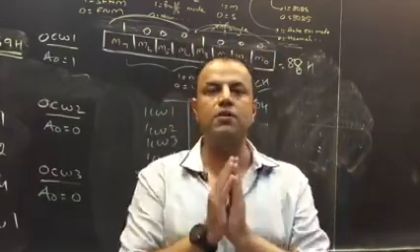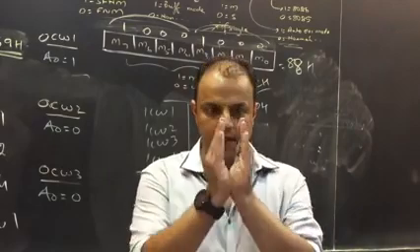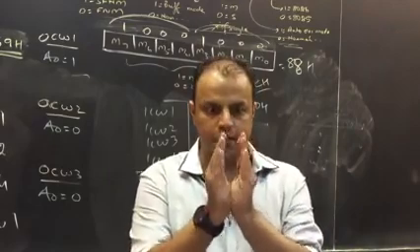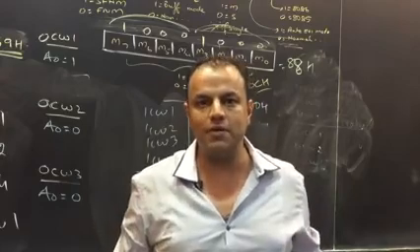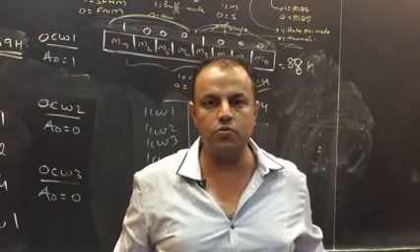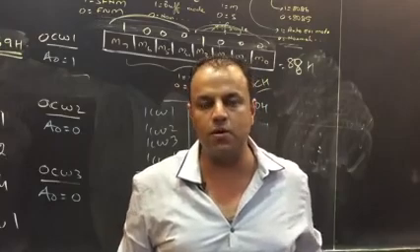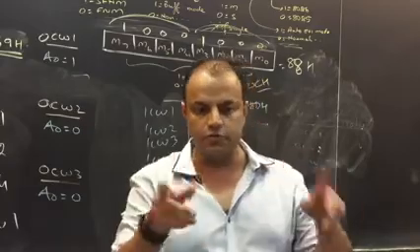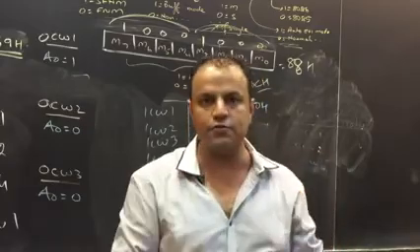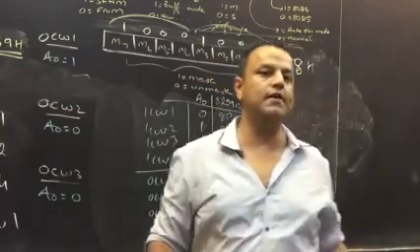But if I give you all the 7 commands at the same address, 80, 80, 80, 80, 80, 80, how will you ever come to know which command am I giving? How will you know whether it's OCW2 or OCW1 or ICW1 or what? Because they're all coming at the same address. These multiple addresses are created so that commands can be given at different addresses so that they can be recognized by 8259. Tell me, so far are you clear?